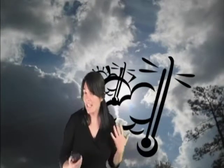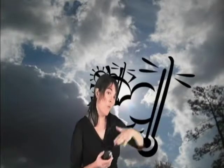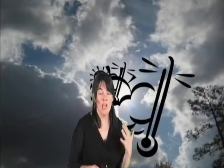Temperature definitely plays a role in solar panel efficiency. Solar panels are rated at kind of a medium level. If you look at a solar panel, it says, okay, this is an 80-watt solar panel. Well, that's assuming that the 80-watt solar panel is operating at an average temperature of around 25 degrees Celsius. So when it drops from that, or when it warms from that, you're going to ultimately have either a more efficient solar panel or a less efficient solar panel. And we're going to do a little math problem here in a minute to show how that works.